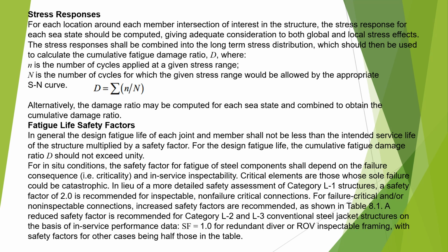So here one thing we need to understand is that the stress response for each location around each member intersection of the structure of interest, the stress response for each sea state should be computed. So we have here each location, each member, and each sea state. So we need to give adequate consideration to both global as well as local stress effects.